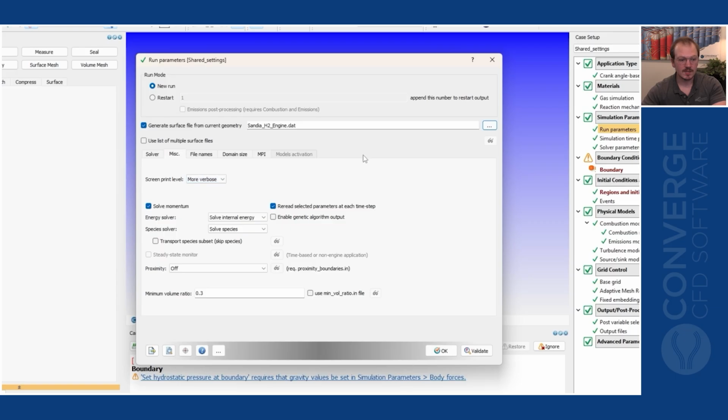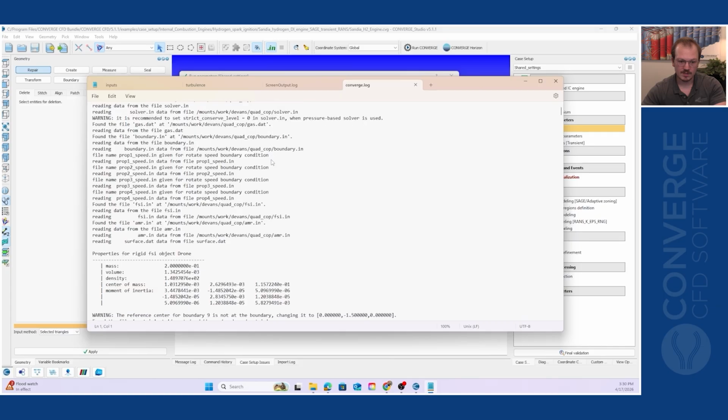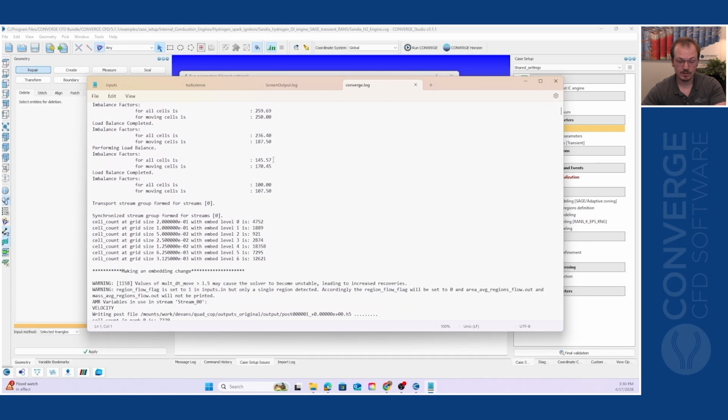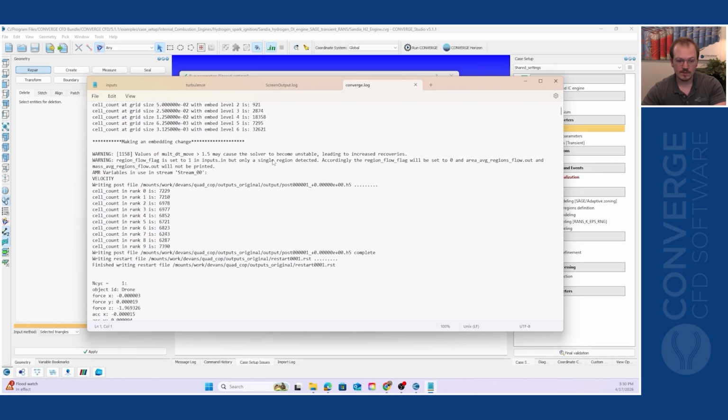For example, verbose adds info about the step-by-step convergence of the iterative algorithm, as well as final convergence of turbulence, species, and passives. While more verbose adds information about convergence information within each loop of the iterative algorithm, including additional information about solving detailed chemistry and where in the simulation domain the recovery or time step limitation happens.